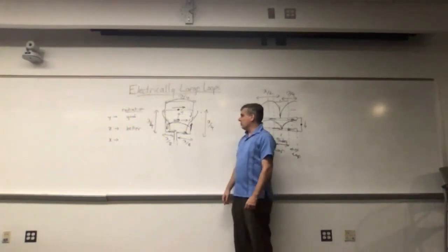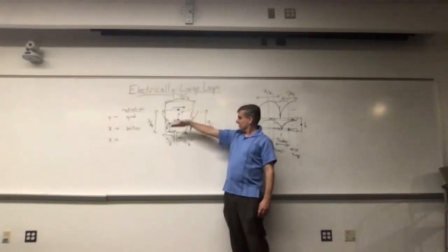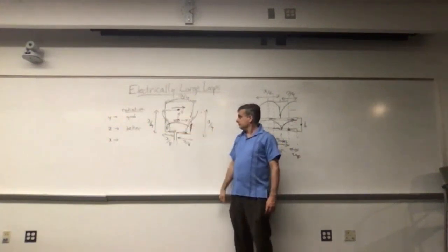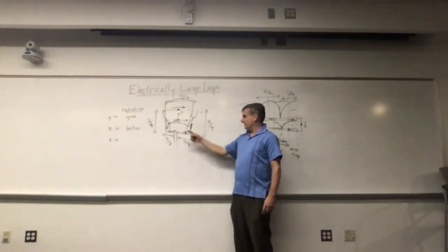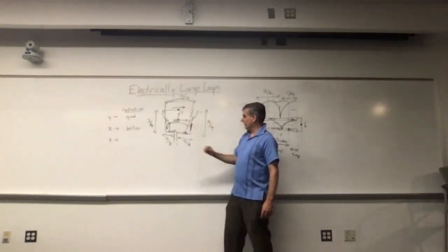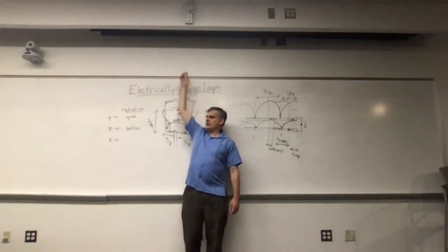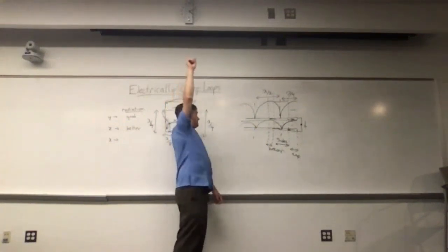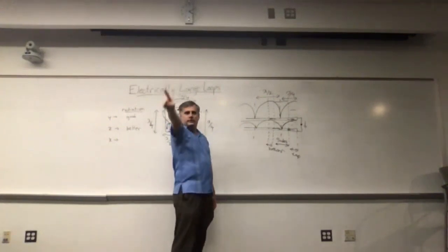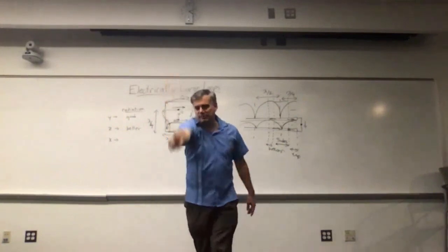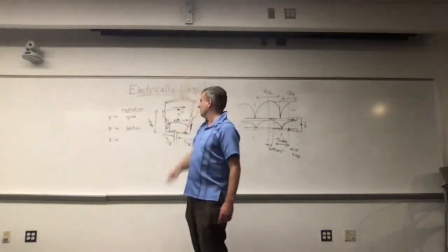But if you wanted outright coverage with your loop antenna, you would like to use it in this configuration, where the field would be horizontal the way I've drawn it on the board here, and the peak gain would be this direction. You would still get some gain. So the elevation cut of my phi hat electric field would be like an oval if I did a cut like this. Maximum, minimum but not a null, maximum, minimum but not a null.